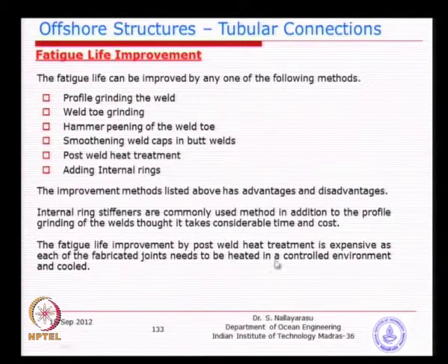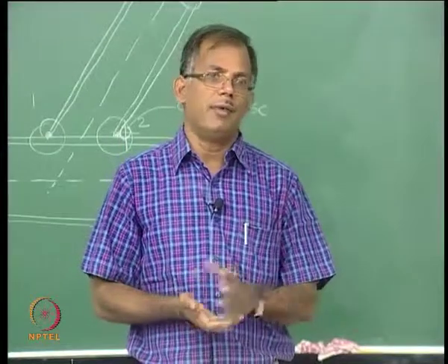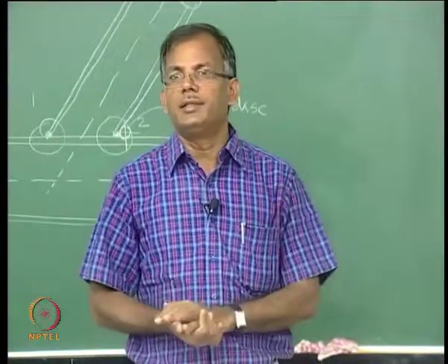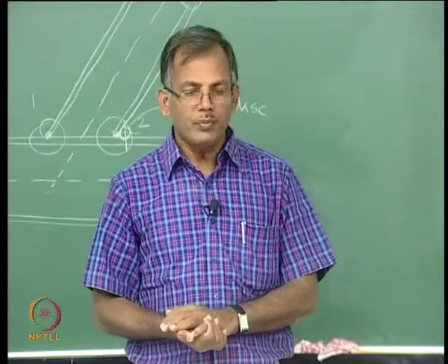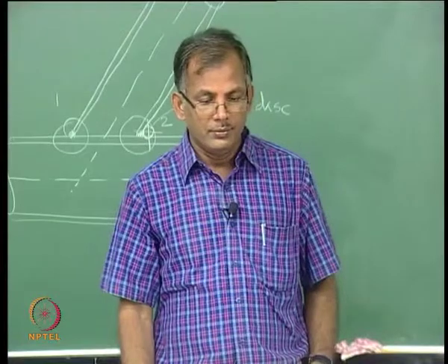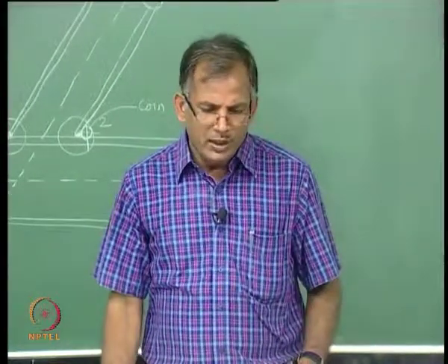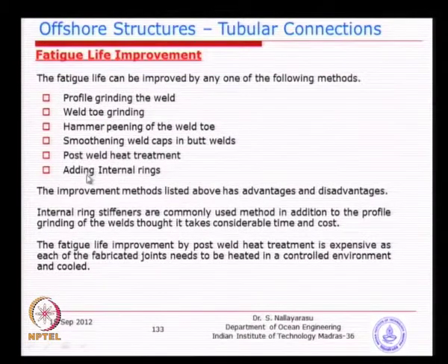Whereas, it is normally used in the mechanical pressure vessel industry, when the pressure vessel is very thick. They fabricate the pressure vessel and heat it and cool down, because pressure vessel carrying large pressures, you do not want to have the higher residual stresses. So, among these, the first one and the last one are inherently easy to apply to improve the design life, whereas the others, though the idea is given, the use of them for real purpose is very limited.